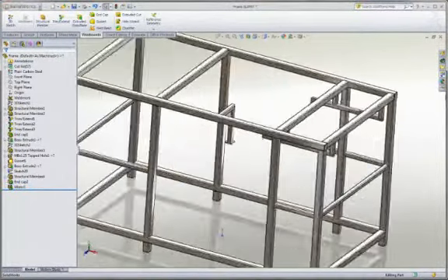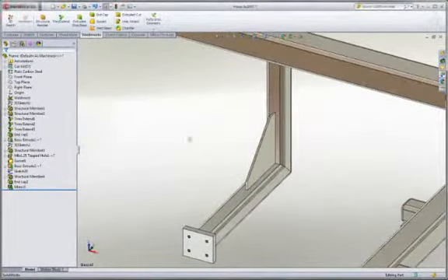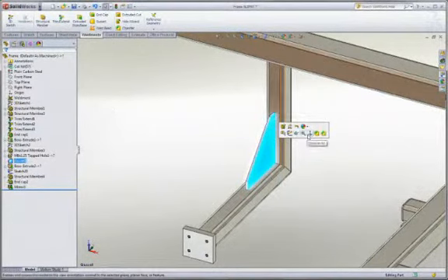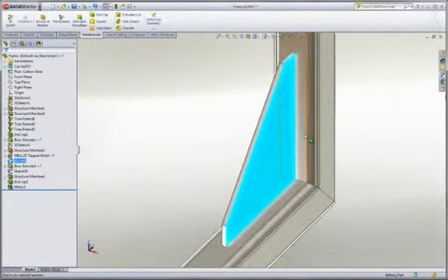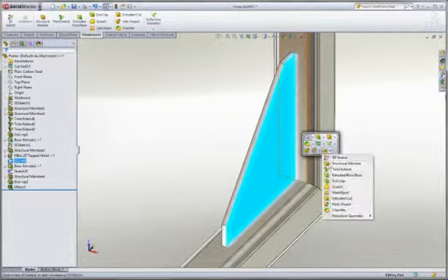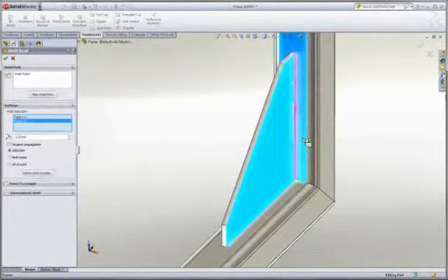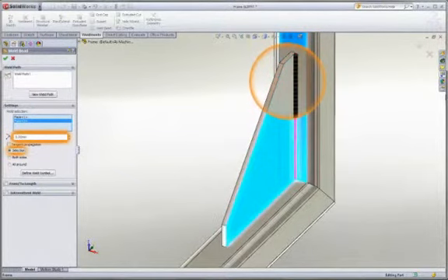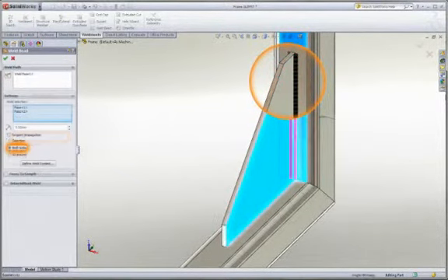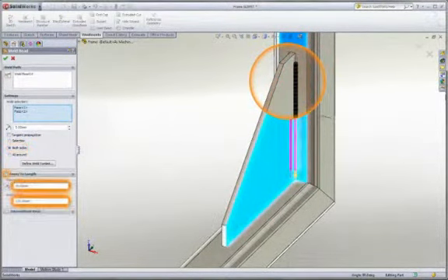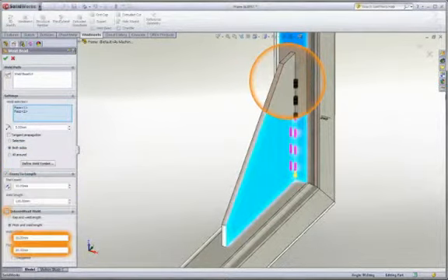We've completed all of the major design elements to our frame, but there's one significant piece missing: the welds themselves. Like every other tool in SolidWorks, we'll see that we can quickly create any type of weld we could imagine, from single straight welds to a weld on both sides. We can control the offset from the ends and, of course, intermittent and staggered conditions.